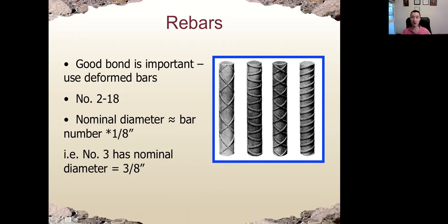Right. For steel reinforced concrete, we need to ensure the steel bar will work together with concrete under the load. Okay, so that means a good bonding is very important. That's the reason why in most cases we need a deformed surface, as we can see from here. So that will provide mechanical bonding between the rebar and surrounding concrete.